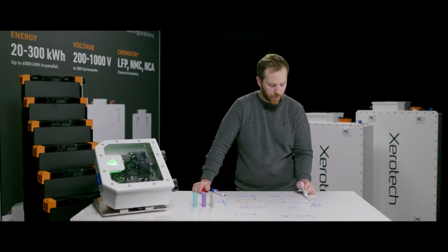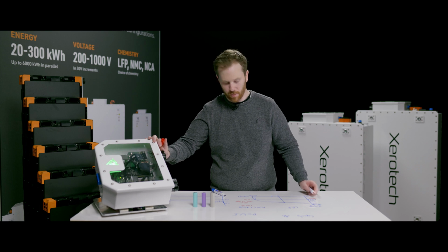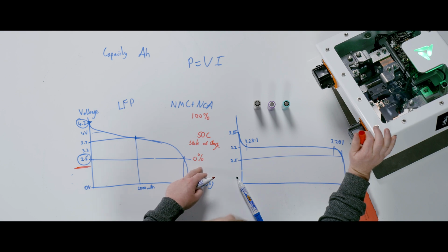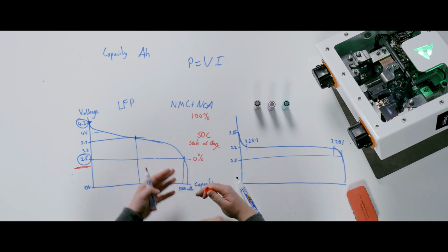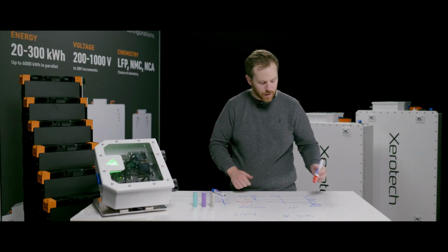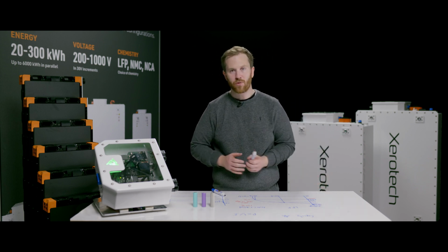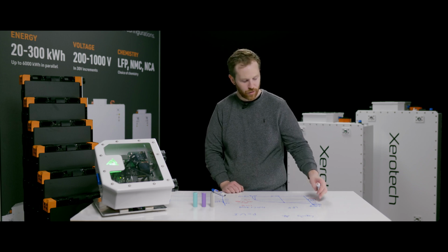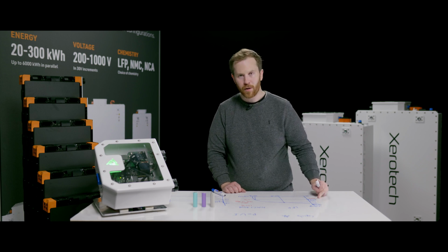This is 100% SOC. So that's the state of charge. The reason you should never ever go below 2.5 volts, and why we have something called a battery management system, is that you cause fundamental electrochemical damage to the battery. There isn't really energy below 2.5 volts. You actually start to damage the cell. It starts to dissolve and many bad things inside of it start to happen. Similarly, when the voltage goes above 4.2 volts, you start to run into new electrochemical faults and issues. So it's incredibly bad and incredibly dangerous to go above 4.2 volts per cell or to go below 2.5 volts per cell.